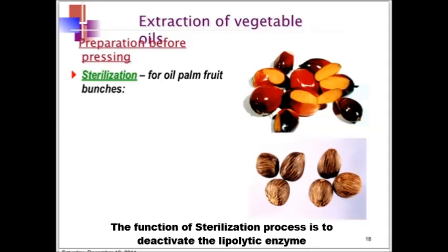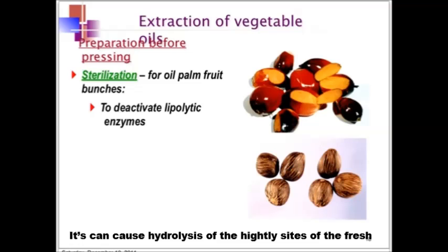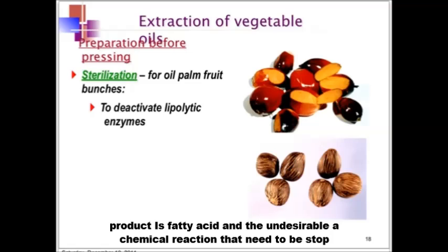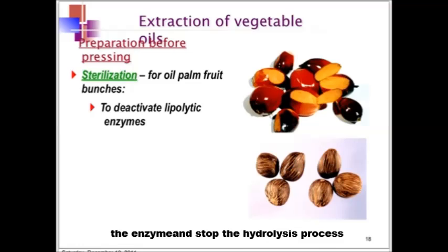The function of the sterilization process is to deactivate the lipolytic enzymes. The lipolytic enzymes, such as lipase, in the oil palm fruits can cause hydrolysis of the triglycerides, or the fat, to produce free fatty acid, and this is an undesirable chemical reaction that needs to be stopped. So by using high temperature in the sterilization process, we can deactivate the enzyme and stop the hydrolysis.